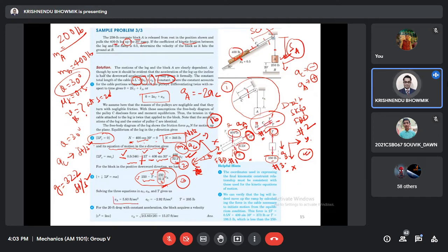That is A, this is the A positive moving down, increasing, AC decreasing, because SC length is decreasing, then T is 205, T equal to 205. Now somebody can check if T equal to 205 tension. And we have considered that it is moving down, correct? Whether it is moving up or not, you can check that one also.